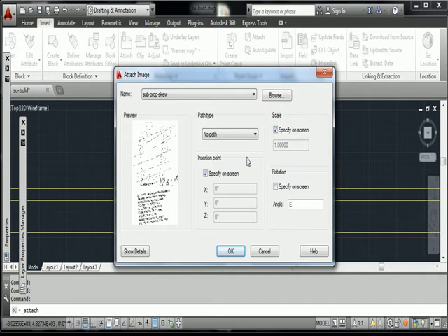If you've been rushing it and put full path on there, that means, let's say you took this file home to work on, right? You were working on it at school right here, it looks fine, it works fine, the image shows up, I can use it, but then you take the file home. You took the drawing file and you took the image file with you. However, it says full path, so it is going to look for that image file in your X drive, because your document is probably saved in the X drive, right?